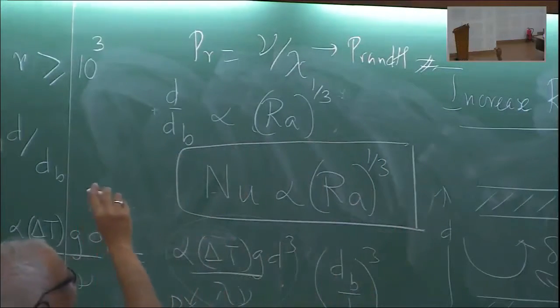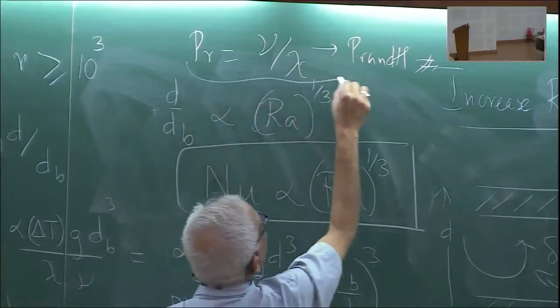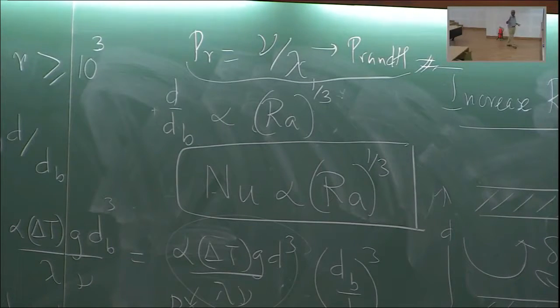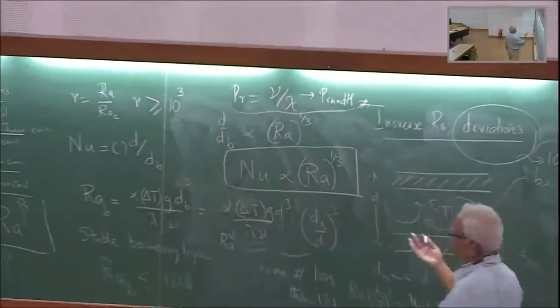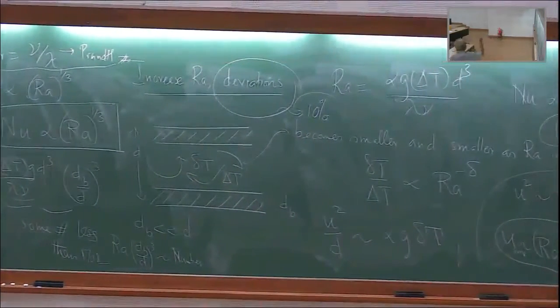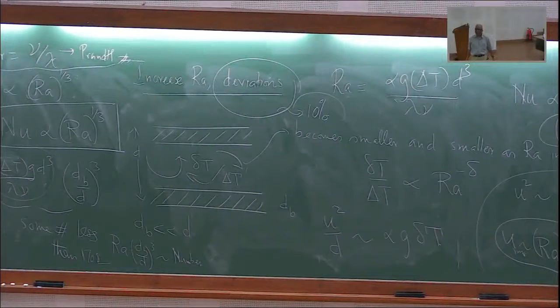So Prandtl numbers can be from very small to rather big, so varying them in the lab from small values, for example, metallic liquids like liquid sodium, when Prandtl number is down to 1 over 10 or 1 over 100, whatever, and up to about 10 or thereabouts for certain oils and things like that.